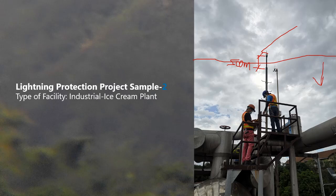If you will notice some other design for a much higher lightning protection system, the pilot light for the warning sign is installed parallel or along the pipe, along the structure. That's the good design, not a separated one. That's why I'm not allowing this one.